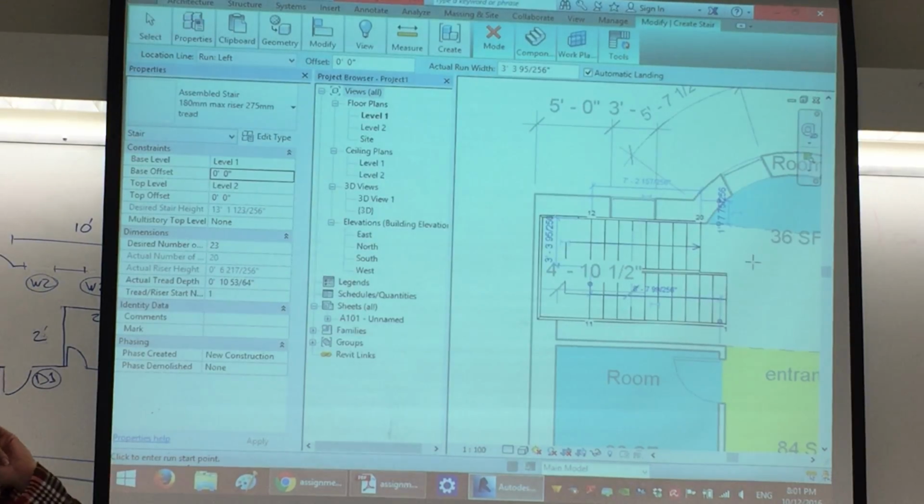So when you specify the first point, because you chose the left, you're starting to draw on the left side. You draw 11 or 12 or 10, depending on what your preferences are. And then on the other side, as a U-shaped stair, you give it a specified distance, you draw the rest. When you click outside, it will draw the whole shape of your stairs.